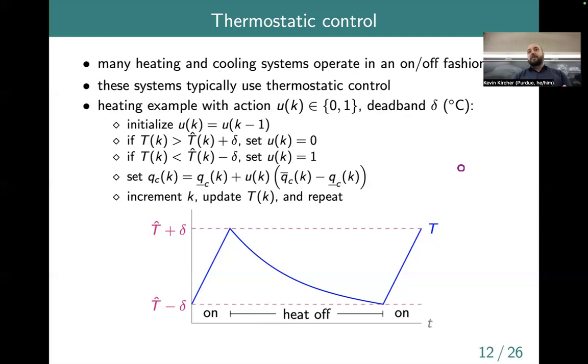Another one would be variable speed equipment. A motor typically can either run on off, or else inverter driven motors can have a continuous RPM range that they can operate through. There, rather than using this kind of bang-bang control logic, you might use something called PID, proportional integral derivative control logic. I'll just talk about the proportional part.